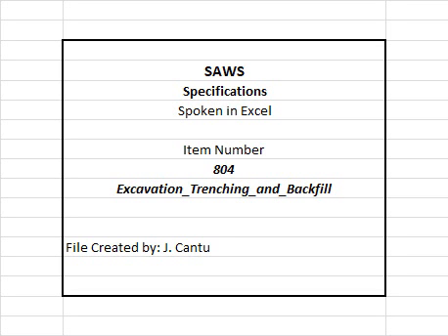E. Where the trench bottom has been over-excavated in excess both vertically and horizontally, beyond the limits as defined in contract documents, the pipe shall be concrete encased or encased as directed by the engineer. 1. Encasement shall extend from the trench wall to trench wall and be a minimum of 6 inches above the top of pipe. No separate pay item. See specification item number 858, concrete encasement. F. Where the trench bottom is not excavated in accordance with this specification due to rock or other hard underlying materials, then the pipe shall be concrete encased as defined in specification item number 858, concrete encasement.